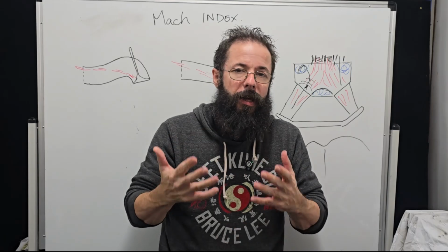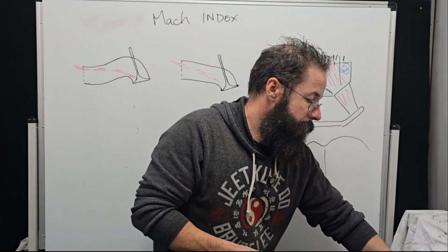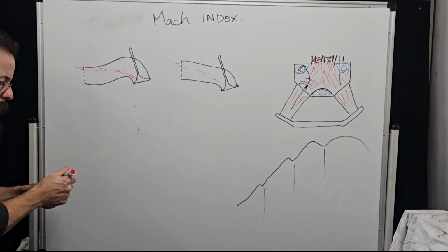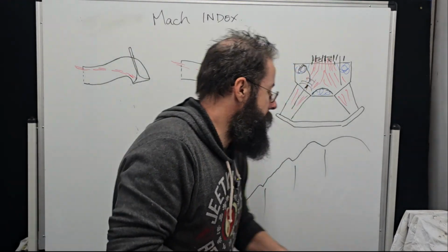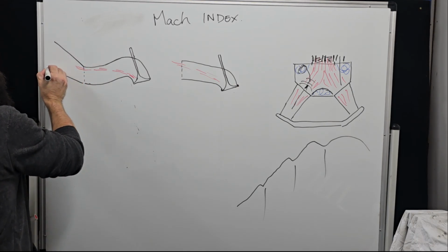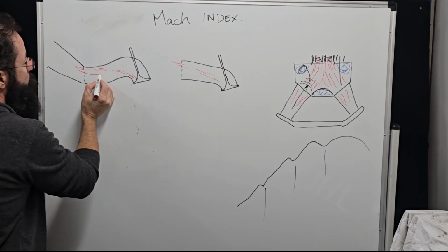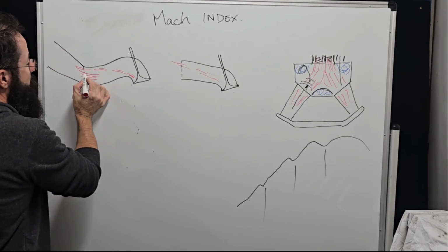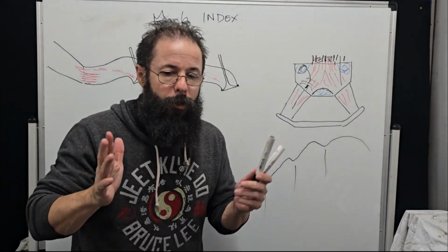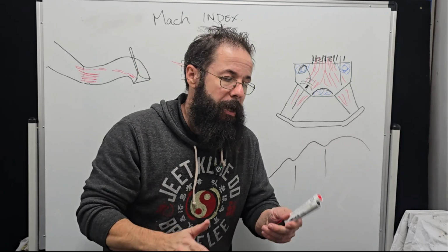But there's another aspect that comes into it, and I'll try and draw it. It's density. When I was explaining the runner angle the other day on the small block Chevys, how we'll kick them up, and that tends to make more torque because we get more velocity down here. Not only do we get more velocity, and this is where there's a little confusion, we get more density for the same velocity.